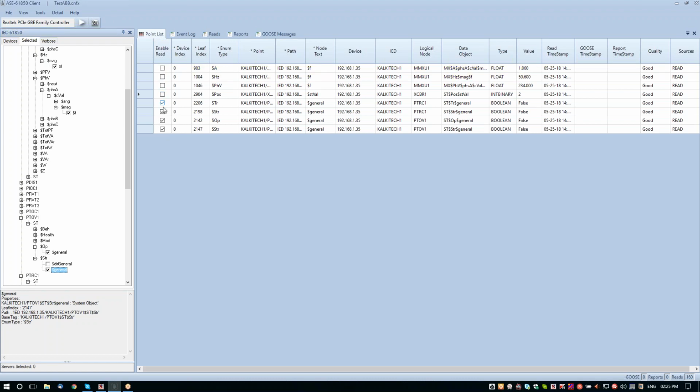To test the reporting, it is important to uncheck this option. We can have both polling and reporting enabled at the same time, and based on the last column indication, the user will know how the data point arrived in the tool. So there could be a toggling between read and report if the same data is fetched through both means.